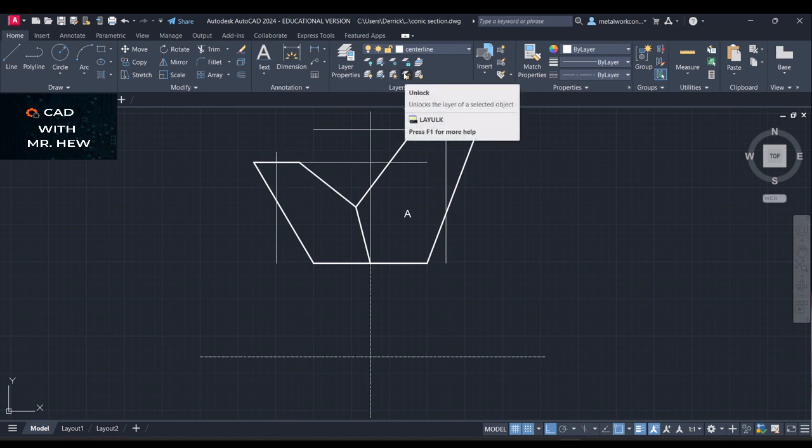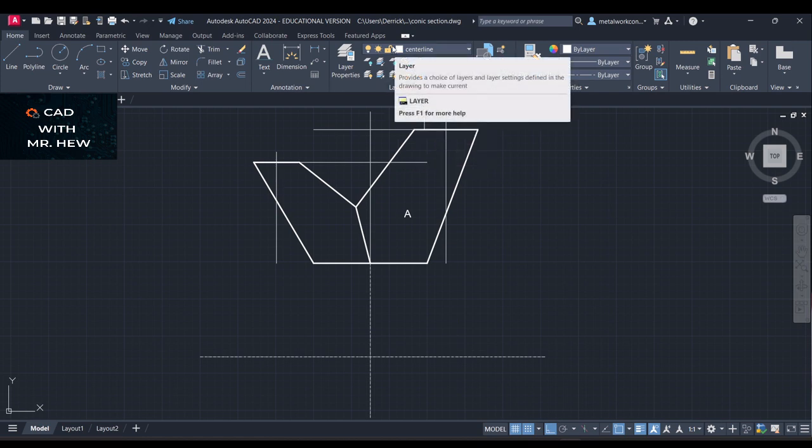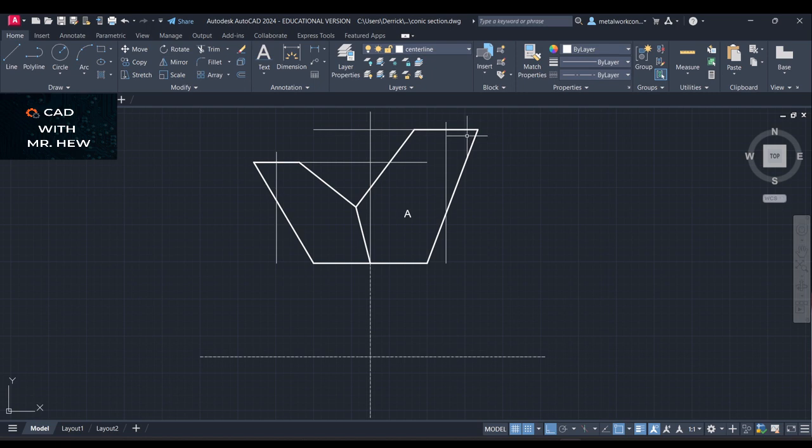I need lines coming down as construction lines from here to there so that I can get the diameter or the radius of the common circle for the two oblique cones. Okay, all right, so we're going to draw our circles now. All right, so that's the first circle.